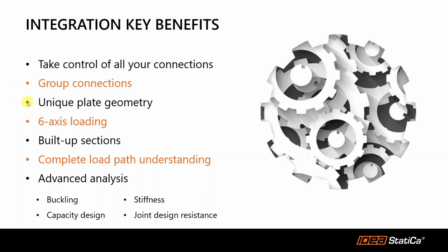By using IDEA StatiCa Connection, you will be able to model those non-ordinary connections that will sometimes include unique plate geometries. Within IDEA StatiCa, you are able to model those plate geometries, or you are able to import those geometries as a DXF file. IDEA StatiCa also offers 6-axis loadings, meaning you are able to analyze your connections based on load combinations without having to resort to load envelopes.